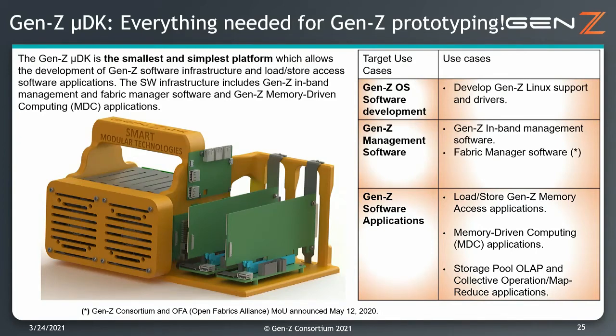This allows the software infrastructure to really become established. I'll show an exploded view next, but in this diagram here it's like an orange plastic box. On the left-hand side are two cooling fans, and those are like parking bays for memory modules. So that's your memory resources. And on the right-hand side of the orange box we have PCI add-in cards, and this allows you to run your processors. You can run one or two cards, and those can communicate with each other and with the memory, sharing the memory, and can really exercise the GenZ infrastructure in quite a small, compact environment.